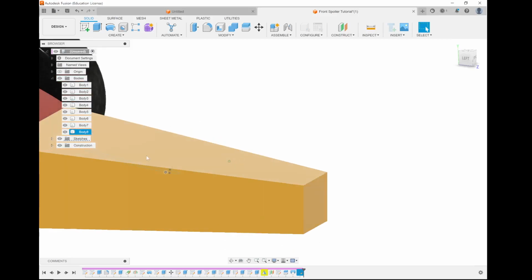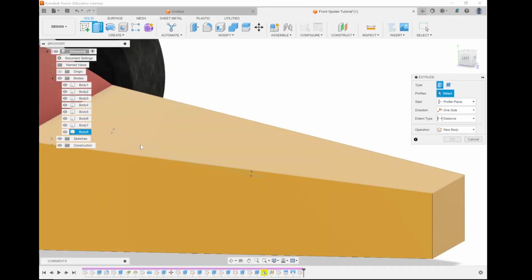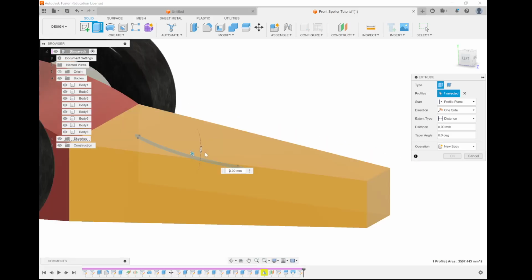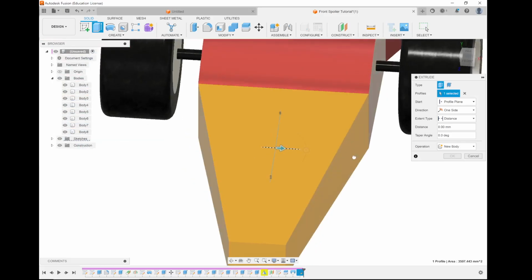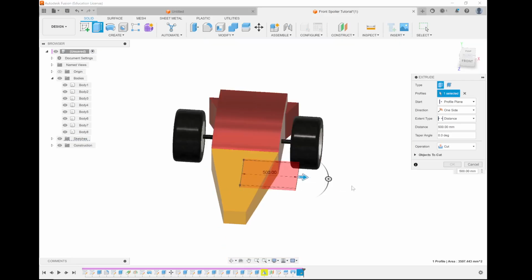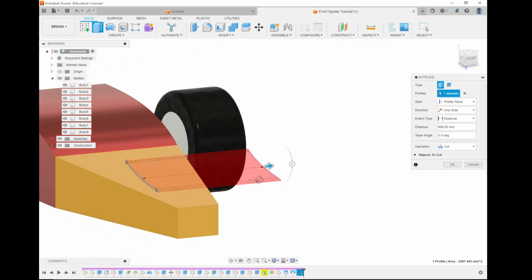So to turn this into a 3D object, we are going to use the extrude. We want to click this profile in here, so we'll hold the mouse button, and if we go there, that's the profile we want to expand. We will send it out this way, and we'll mirror it later. So you've got to choose how far we want this to go out. Probably just making up a distance, that far looks fine.